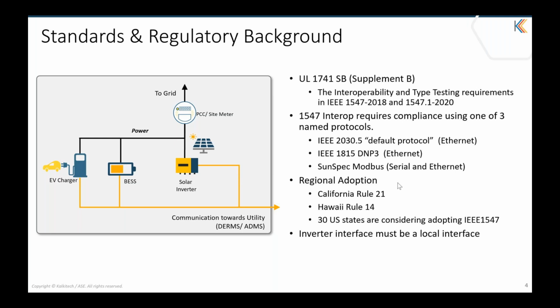In California, all DERs above 1 megawatt should send telemetry data to the utility, and as part of phase 3 of Rule 21, there's also a mandate for the control functions to be implemented. California IOUs are required to provide customers with customer-owned telemetry options to send telemetry data to the utility. These are some of the driving factors for interconnection of DER with the utilities.